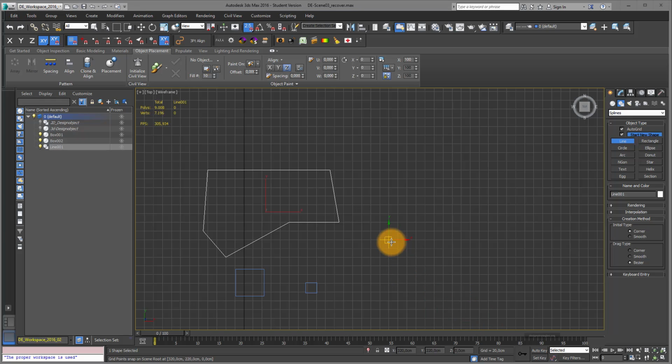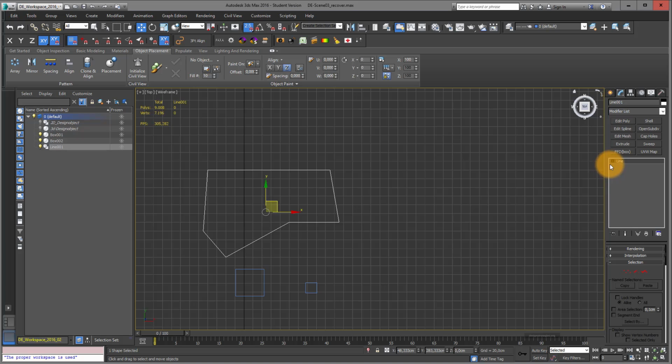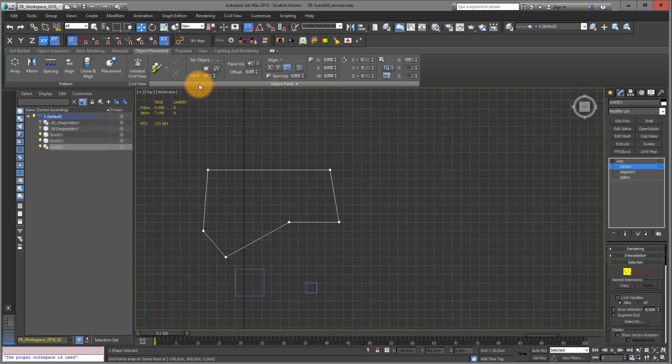Okay, now that we've drawn this line, let's see how we can adjust it. I go into my Modifier tab, open my line context menu, and choose the vertex points in the hierarchy. With my snap function on, I press the S button and choose deselect grid points. I select my vertex point, and I have my axis align constraint on.